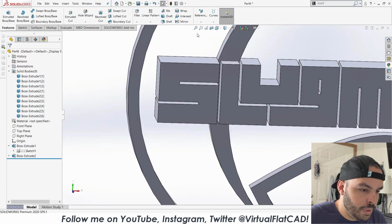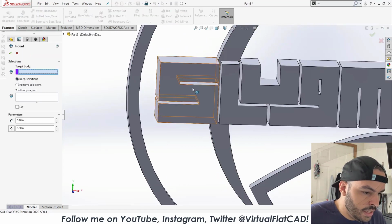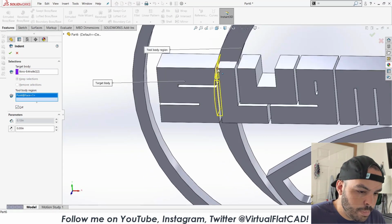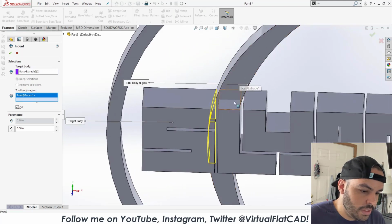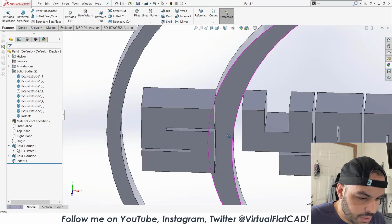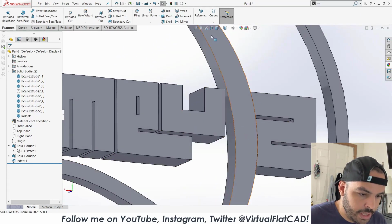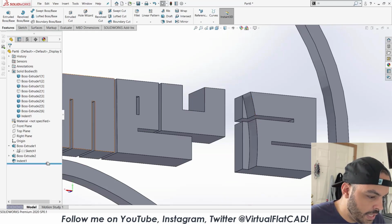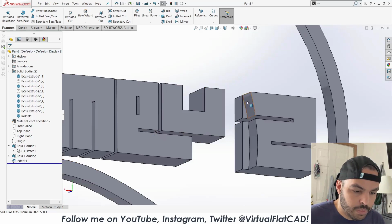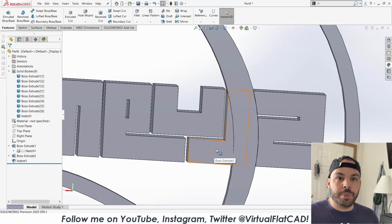And maybe just to clean it up a little bit, I like to use the indent command. Indent, I can get this S, and if I turn on cut, it'll make a pocket that will perfectly fit this thing that is going through. So I'll give you a Jumbotron close-up. So just kind of remember where this is. I'm gonna hide it. So before they were intersecting each other like that, and afterwards a perfect pocket. You don't even have to really think about it. It's just based on the position of the body.